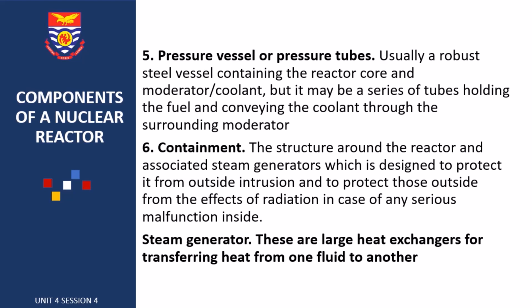The next component is the containment, which surrounds the reactor and the associated steam generator, and it is designed to protect this reactor and steam generator from outside intrusion and to protect those outside from the effects of radiation in case of any serious malfunction inside. The steam generators are heat exchangers, and they basically help to transfer heat from one fluid to another.